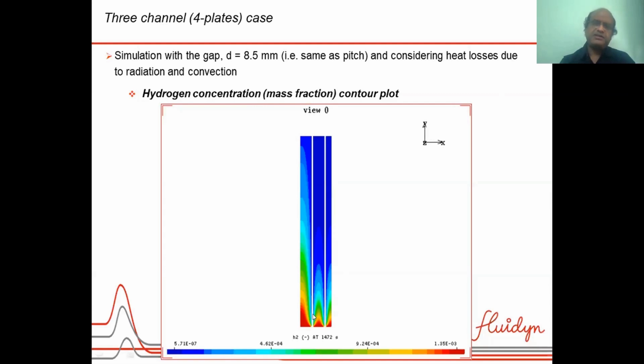As the hydrogen gets reacted and depleted at the surface, the hydrogen from the surroundings diffuses onto the plate, and that also gets converted. So as you can see, the hydrogen concentration in different plates is not the same. There are side effects, etc. So the whole problem has to be solved. We cannot use symmetric conditions everywhere. That has to be judiciously selected.